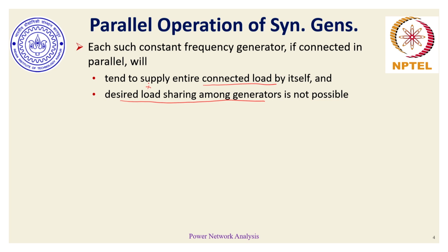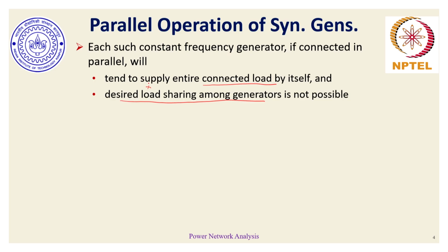So within 1 hour, let's say in 5, 10, 15 minutes, if load is changing and generators have to economically optimize their schedule while ensuring parallel and synchronized operation, the load sharing might appear to be uneconomic in between those intermediate steps where the economic dispatch schedule is unavailable.